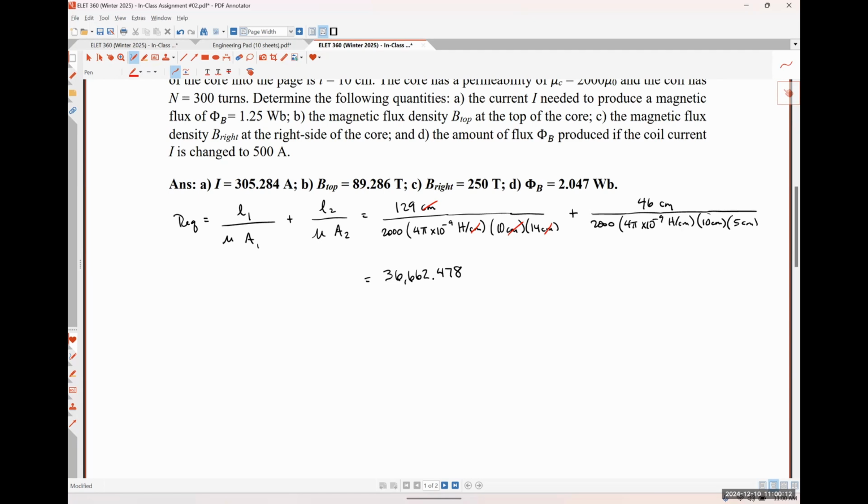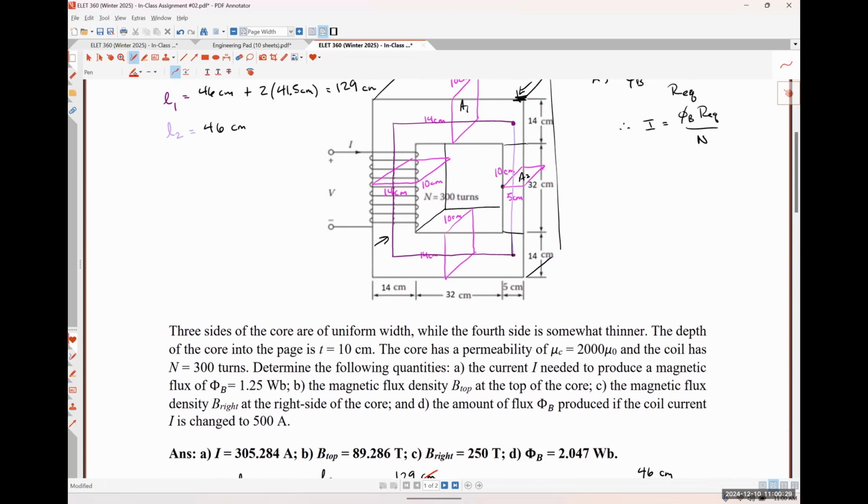So it's looking like I'm going to have units of per Henry, okay, which isn't wrong, but this is another one of those weird cases where we call it something else, even though it's dimensionally the exact same thing as 1 over a Henry. So just as a quick aside, you guys may recall from the 280 course that 1 Henry is equal to 1 volt second per ampere, right? Well, we learned in class on Thursday that a volt second is just another word for a Weber, okay?